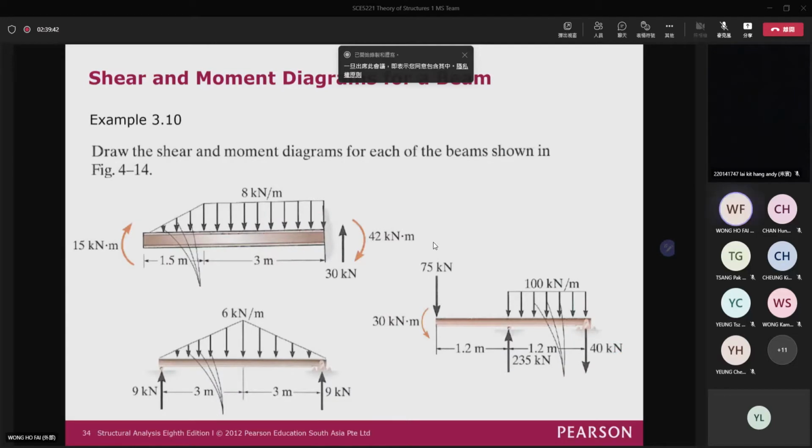And then for here, again, there are several examples that we can find for the shear force and then for the bending moment diagram. Right here, all the support reactions have been solved, and then you can draw the shear force and the bending moment diagram immediately. For here, without going back to the answer, first of all, for the shear force diagram, you can imagine the first stage has no shear force, so you start from 0, right?